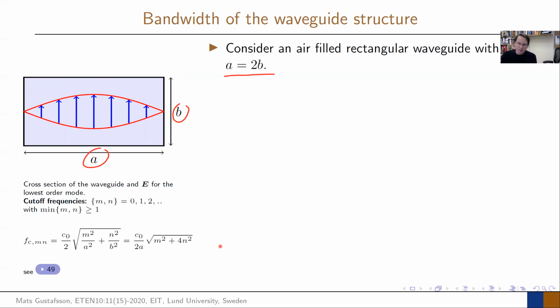We can again get out the cutoff frequencies here, so we can solve them. And in these cases, you can see these modes here, M and N. Think about those as the Fourier expansion. So the higher the mode, the more and more oscillations. You will get a higher mode here that basically could look something like this. There will be a higher mode, so that will have M equal to maybe 3 or something. You want to sit at the lowest one, so M or N equal to 0 or 1. That's what you would like to have.